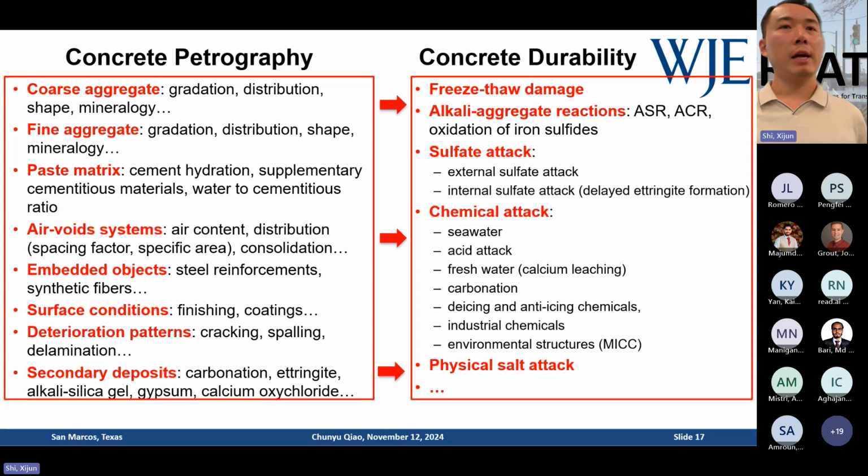So you have alkali silica reaction, you have alkali carbonate reaction, or these days in the New England area in this country or part of Canada from some specific quarries, you have some rocks containing iron sulfides, which can be oxidized in the concrete, give you some other aggregate reactions, which can be a problem in specific regions, not here necessarily in Texas, but for example, Connecticut, Maine, those states.